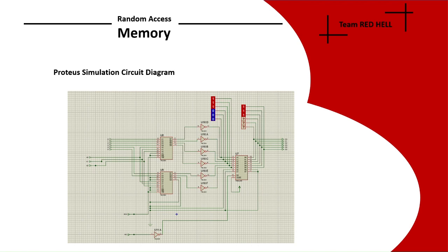Here we can see that write enable is active low. We can say that if the input is 0, write will be enabled, and if the input is 1, read will be enabled. We have another pin we discussed before, which is memory enable, which we grounded. It is active low, so we enabled it by grounding it, and as we don't require to turn off the RAM in the simulation, we kept it active throughout the simulation.